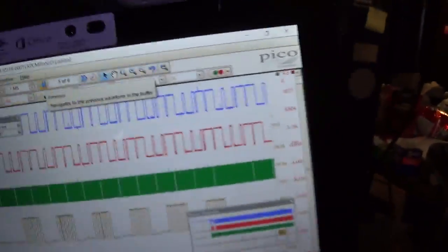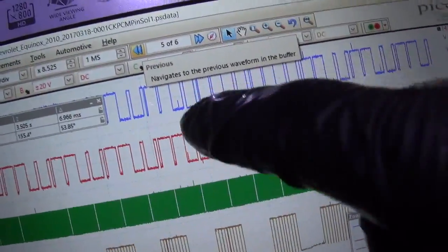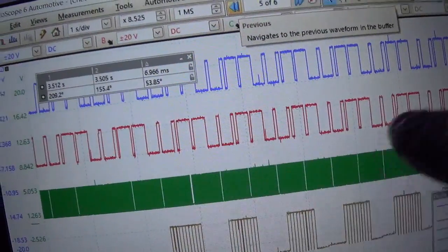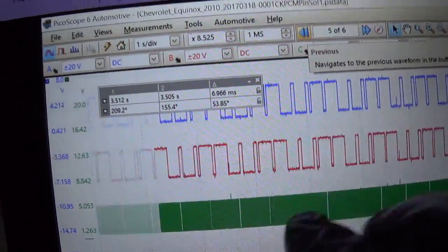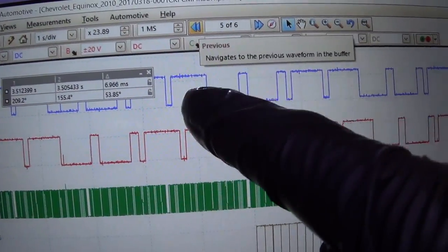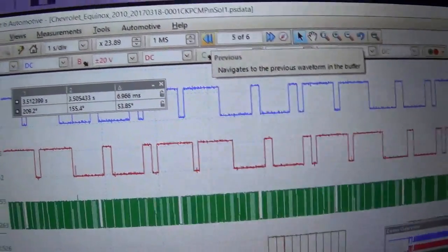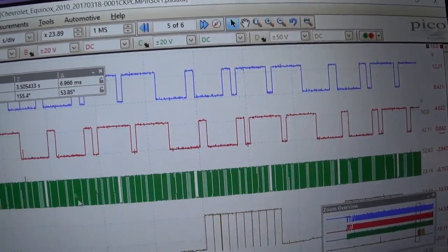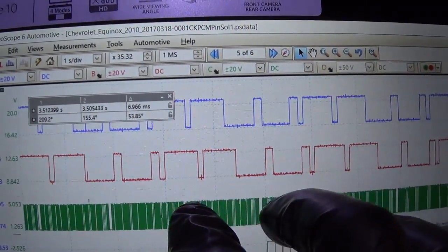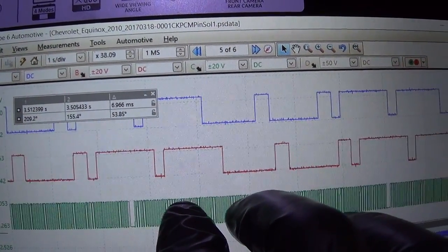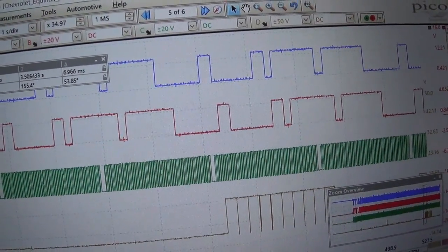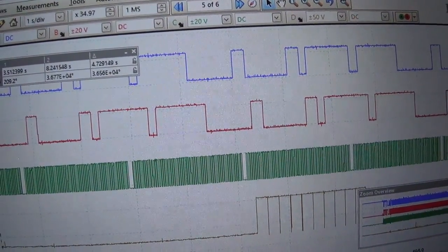We can actually see if it's moving by looking at our camshaft position traces. So right here we're not actuating anything, and the intake is that far. I guess we can put in some cursors. How do we want to do this? So let's do the same degrees of crankshaft.